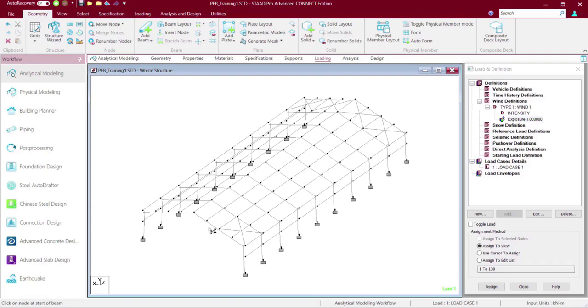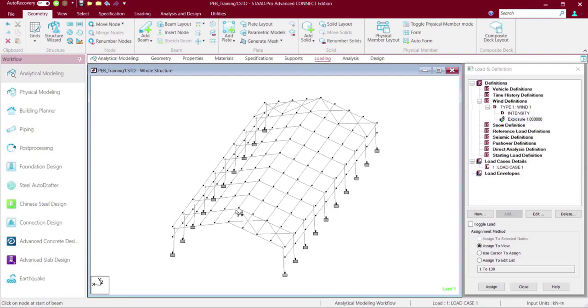So this is just a demonstration. Maybe in a real life model, you will add some different procedure or some different patterns of bracings. So these are for the roof, and similarly, we can go to the opposite end. Now you can see that these extreme ends are braced at the roof so that the building can't have some torsional movement. Although there would be a certain degree of torsion, this kind of bracing would stiffen or rather resist any kind of significant torsional activity.